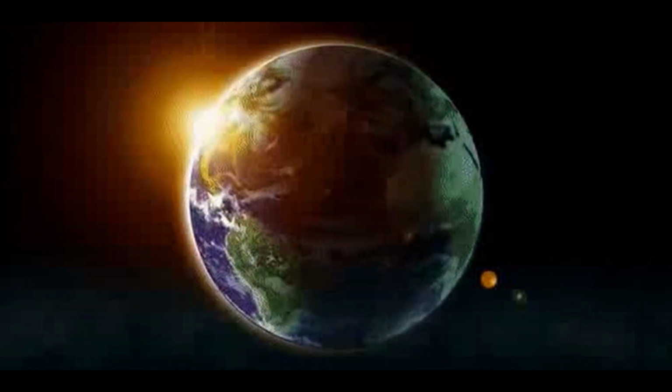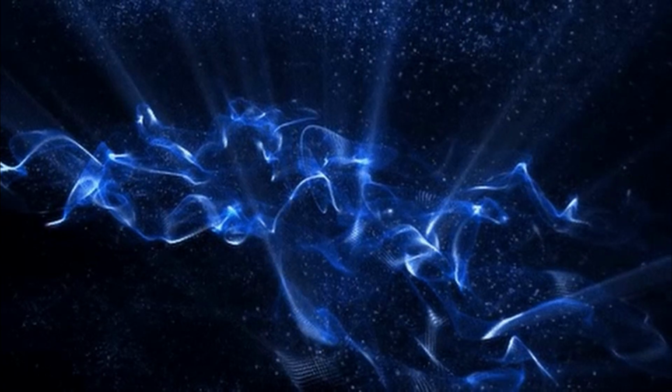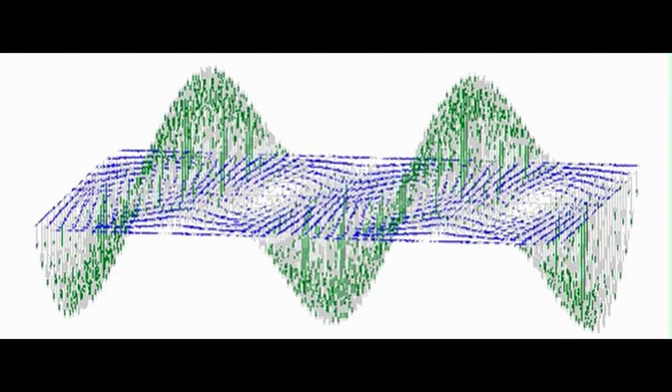3. Suppression of conductance. At low bias voltages, the Coulomb blockade suppresses the conductance through the quantum dot. This suppression occurs because the energy required to add an electron to the dot is not available, preventing electron tunneling. As the bias voltage increases and exceeds the Coulomb blockade threshold, electrons can tunnel through, and conductance resumes.